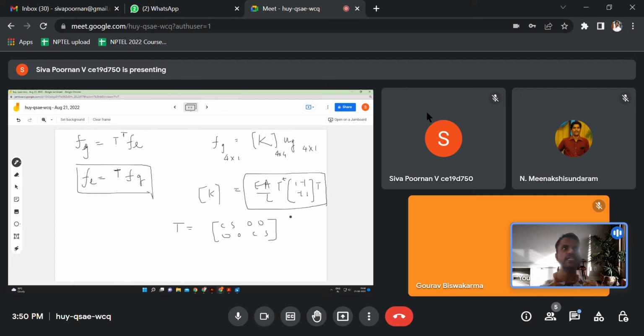So basically once we know this, we are able to find out the stiffness matrix in the global coordinate for any truss member inclined in any direction. So what is the c s? It is cos theta, which depends on the inclination of the truss member. Now we can just name this as theta x, and the other angle along the vertical direction to be theta y.